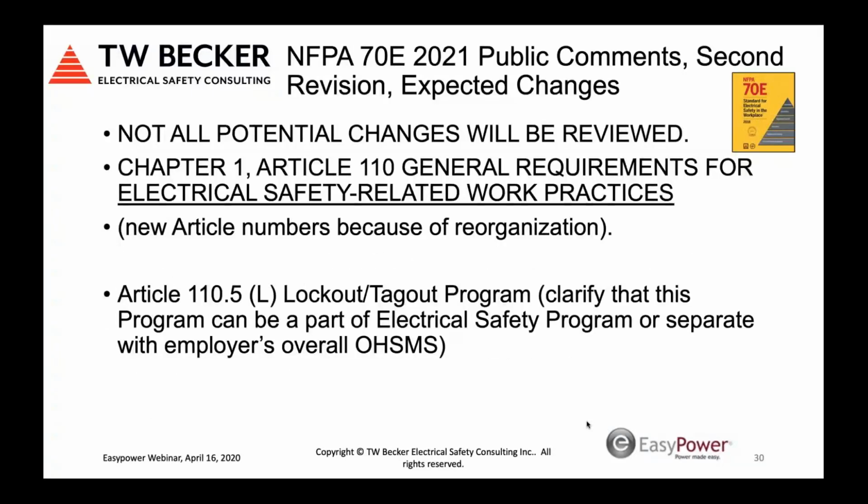So again, Article 110, the lockout program, there's some clarity that under your electrical safety program, a lockout tagout program could be included with the electrical safety program, or it could be a separate document, part of the employer's occupational health and safety management system. And you'll find that lockout tagout programs are separate documents, right? And my opinion is they should be. So it just clarified that that's how this could be provided, embedded with the electrical safety program, or as a separate document.